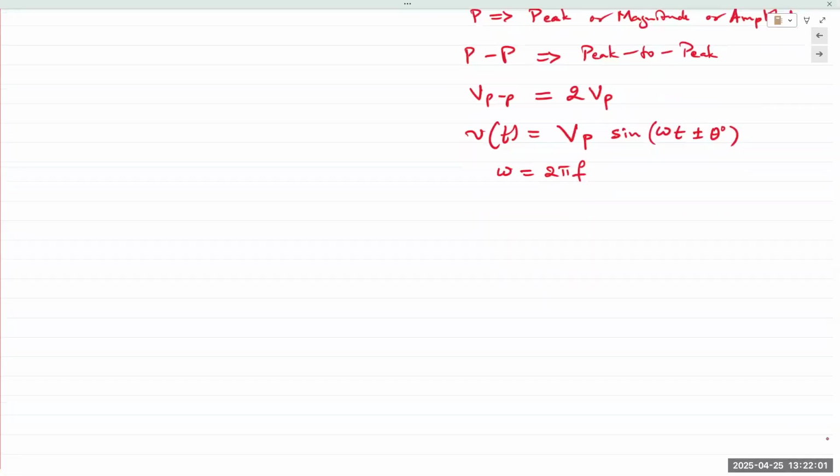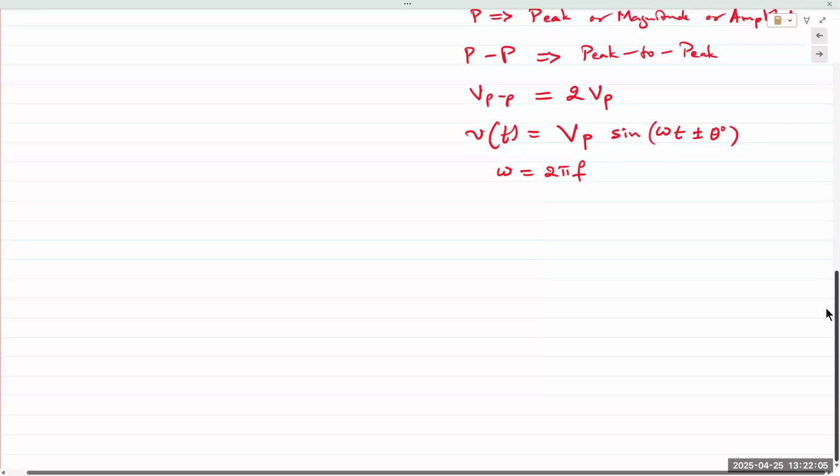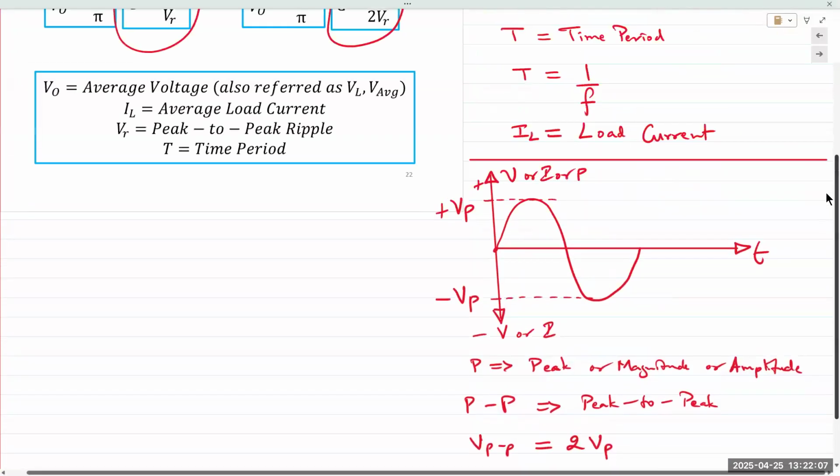Anyway, the way this applies to us is, if you take the average value of this waveform, what do you obtain? 0, right? Yet, when you send an AC signal to a resistor, power is supplied to that resistor, right? So how do we represent that power? And so you have the term RMS, the root mean square.